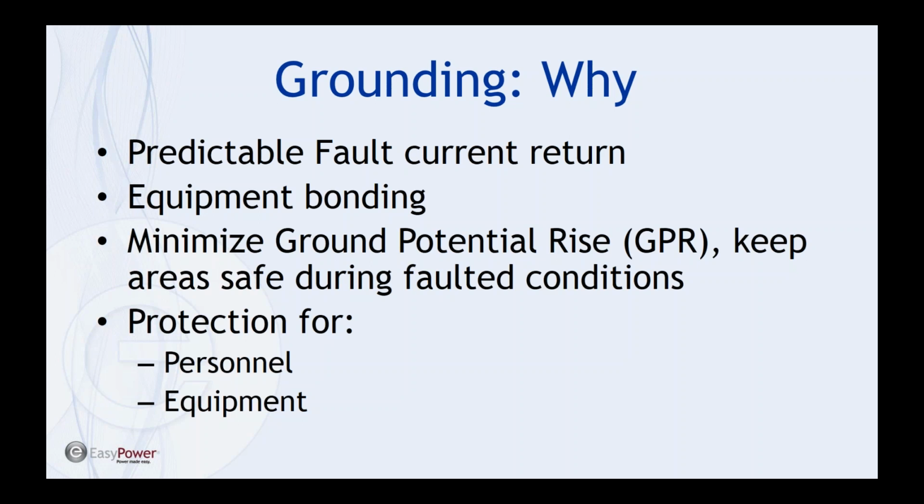Low resistance ground grids, more copper in the ground or a well-designed ground grid, can help keep local ground potential rise lower, which can help with step and touch safety, but it also provides a low resistance path for voltage surges such as lightning and transients. In summary, all of this grounding design and connection of metallic objects contributes to the design of a system that is safe for personnel and helps minimize the damage and interruption during system faults or other abnormal operating conditions.